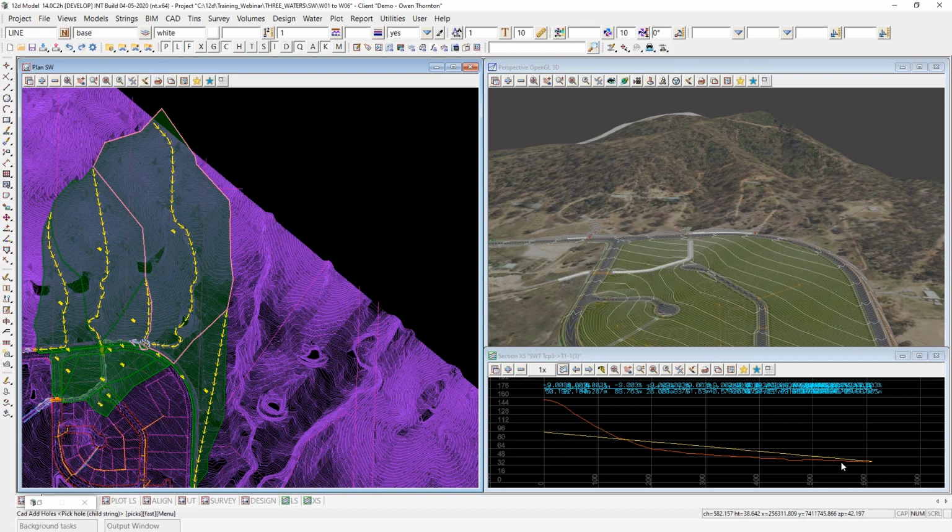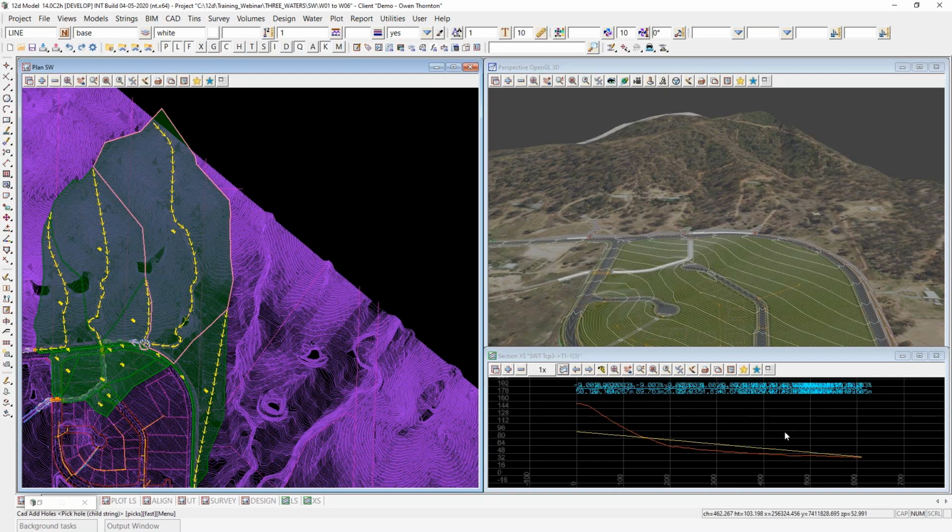Okay, if this is the average slope, it would go from all the way up there, all the way down to there, and that would be much, much steeper. But because this is a catchment that's very steep at the top and then flattens off, the equal area slope is a bit flatter than that, which supposedly gives a better prediction using all these various weird and wonderful time of concentration formulas. Okay, so that's a little bit about TC strings.